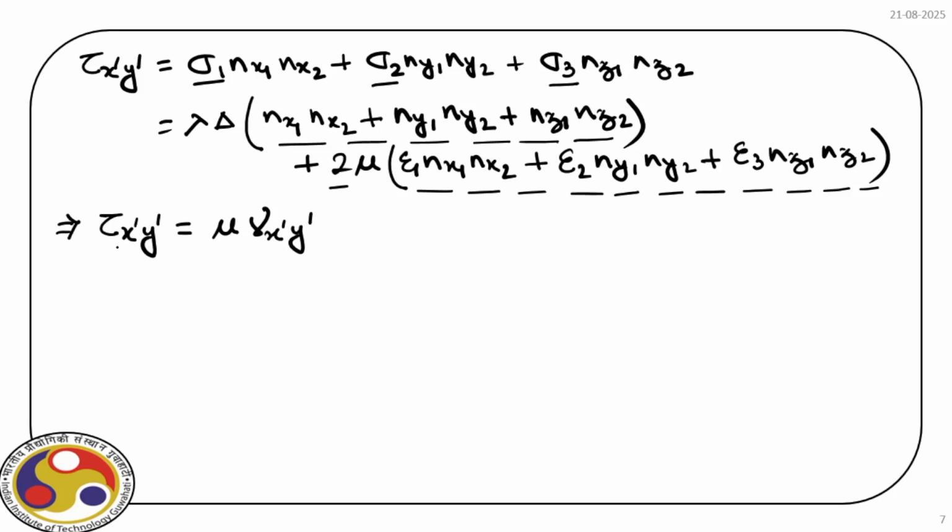This is very important because shear stress on the left hand side is actually related to the shear strain, right? Similarly, we can write down the expression for all other shear stress components, but for the time being, if we refer to our elementary strength of materials, when we correlate shear stress with shear strain, the constant we have is what we call shear modulus, right?